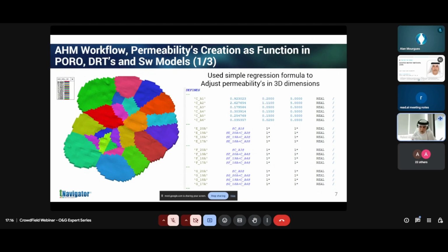Of course, some assisted history matching tools, once they get a good result, freeze the parameters within that region, while they continue the enhancement work for the regions showing a very bad objective function. Mainly, the objective function is the difference between the actual data and the output of the simulation run with these adjusted parameters. So at minimum objective function values, you have a better and better match to the data.